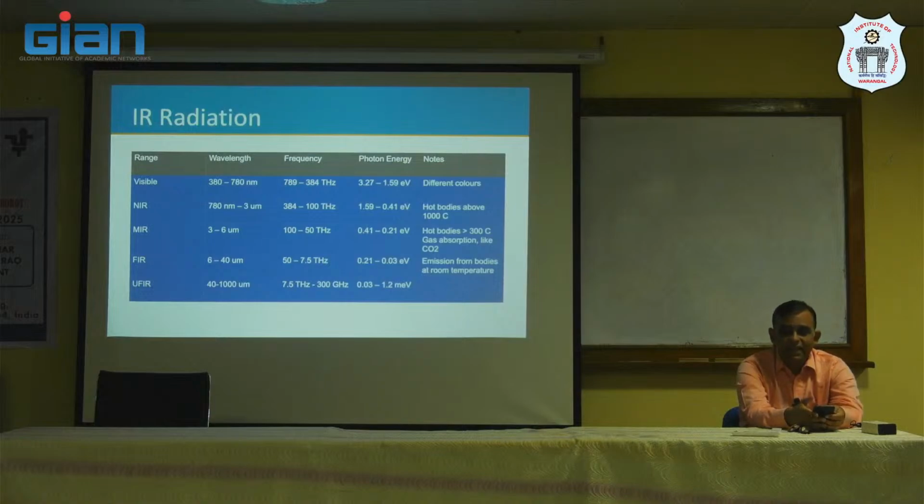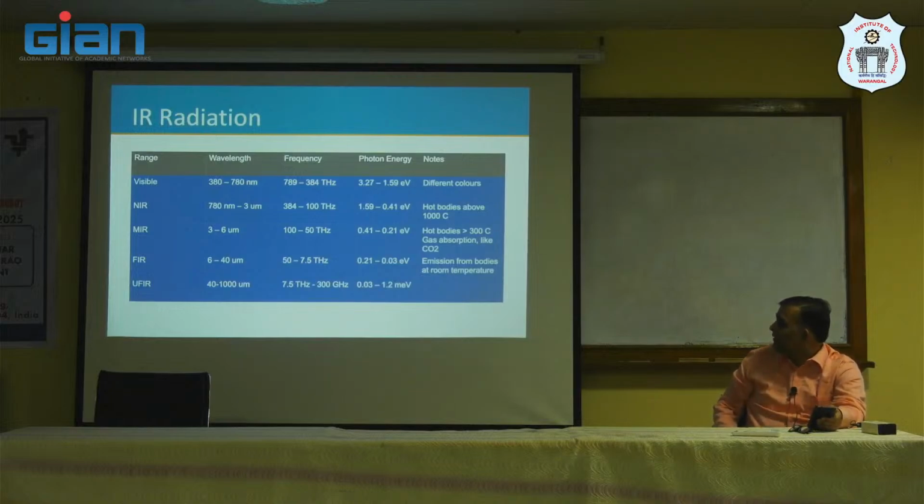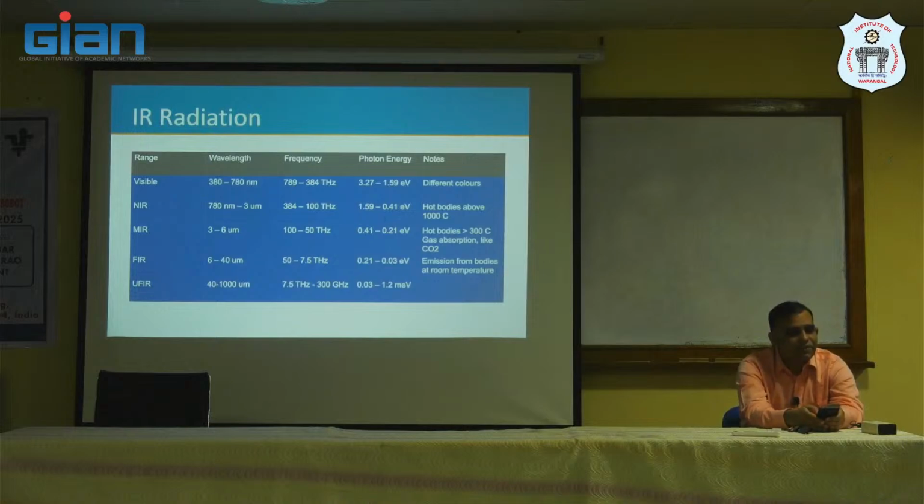But these indium based sensors can act on these devices. Can we go even higher? Can we go till mid infrared? So you have got a table on your phone, mid infrared goes till about 0.21 electron volt. Can we use such materials for that kind of sensors? Is there any material which can do that? Now that would be lead based, which is